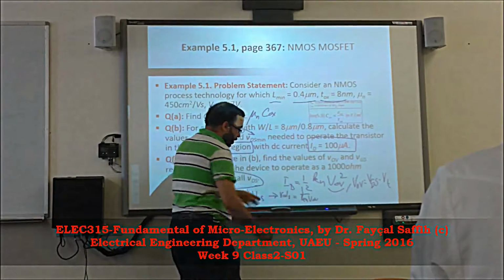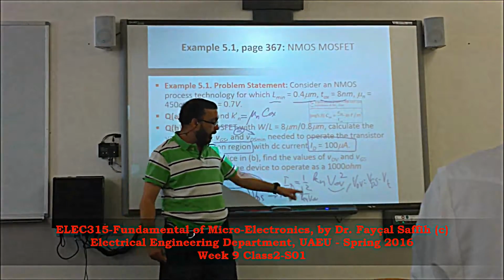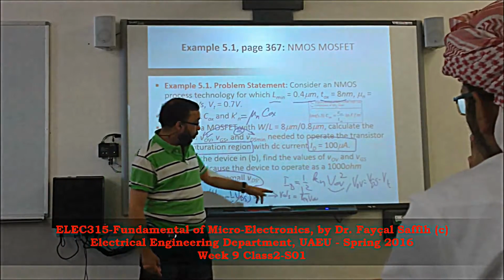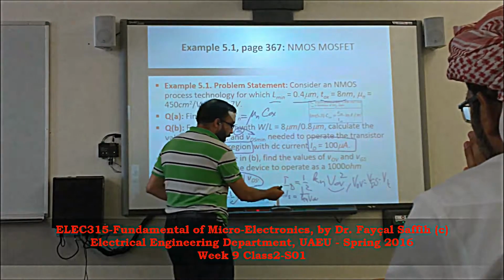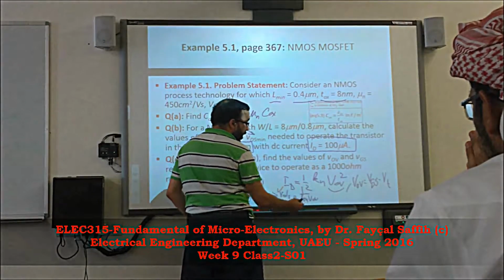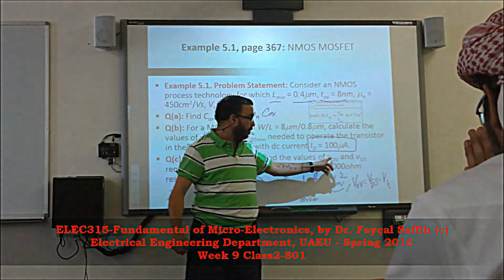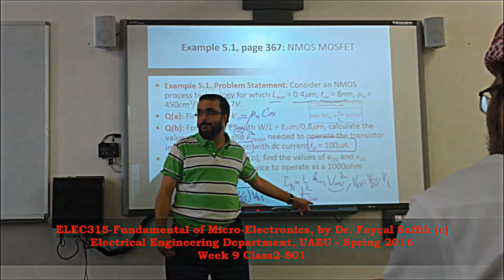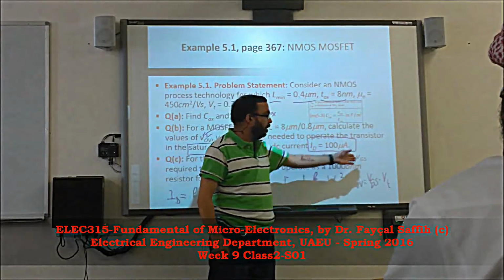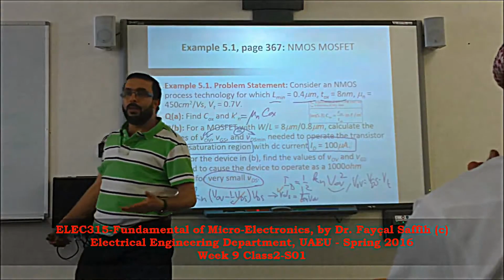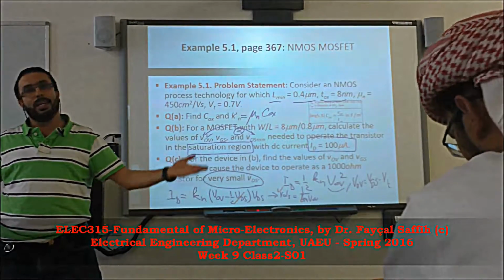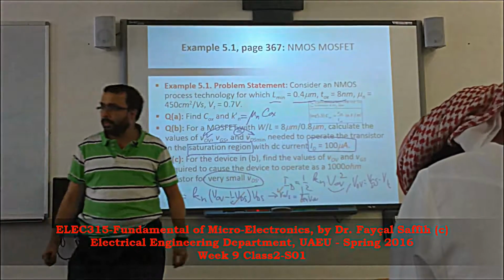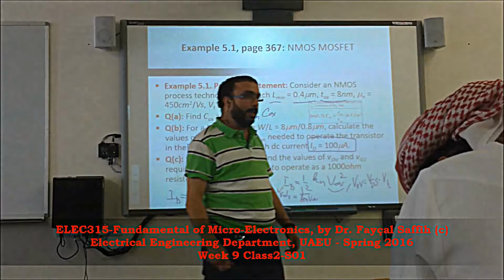So this is the channel resistance. Now Kn doesn't change, it's a constant parameter, as we calculated already. We have R, we have Kn, and the question is to find the overdrive. From here I can get it. Makes sense? We can use it to find VGS. Once we get the overdrive, VGS is nothing but the overdrive plus VT. And the problem is solved. You see? Just in 5 minutes. Clear?